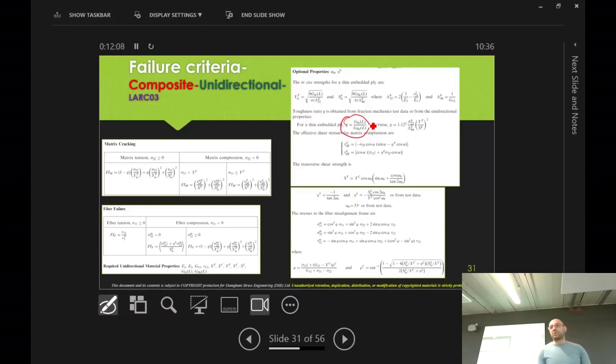So for delamination, we just use finite element software. They call it cohesive zone modeling. So we model delamination, the delaminated layer or potentially delaminated layer, and see if it delaminates or not. None of the failure criteria that I will discuss says anything about or mentions delamination. They're not capable of doing that. Even this NASA developed one.